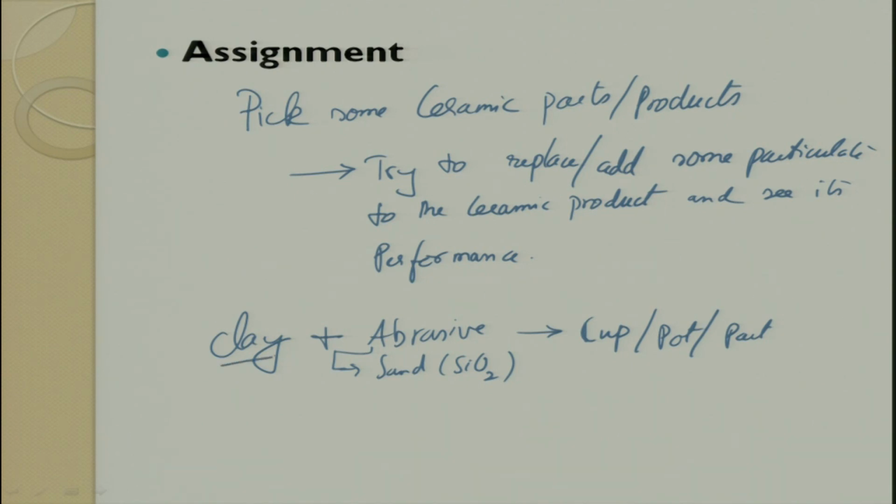So, first take clay, and then you try to fire the clay. The firing of the clay can be done in a microwave oven, or if you have a furnace, you can put it in a furnace and maintain it at a slightly higher temperature, around 800 degrees Celsius. We are not looking for a very sound quality, but just for your understanding and experimentation sake. Or you can just put it in a microwave oven and keep it for some time, maybe 2 or 3 minutes, and before it forms any cracks, you have to pull it out of the microwave.